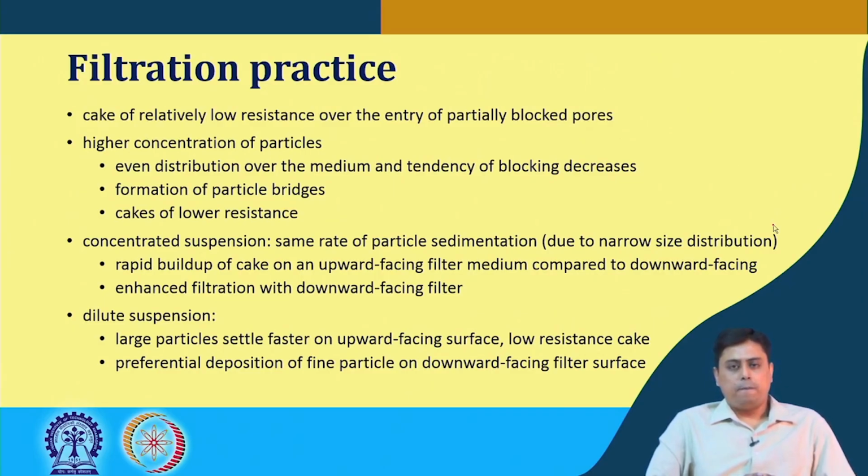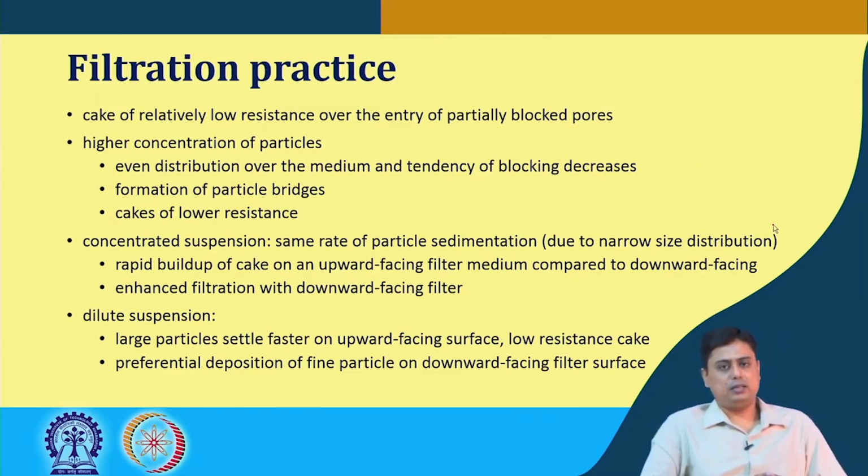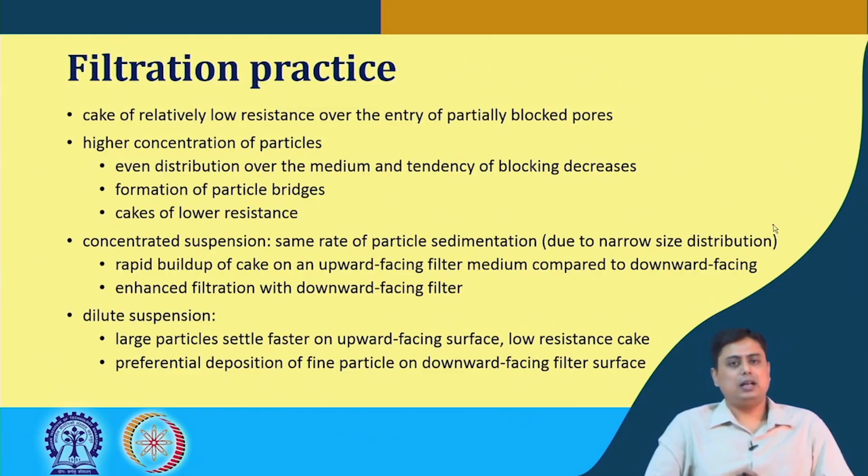Now, particle concentration in the suspension has a significant influence on the cake resistance or the filtration rate. In the overview of the introduction we have mentioned this, but let us see why that happens. When there is a higher concentration of particles, the distance between two particles is very close, so it is difficult to streamline these particles towards the pores to block them.